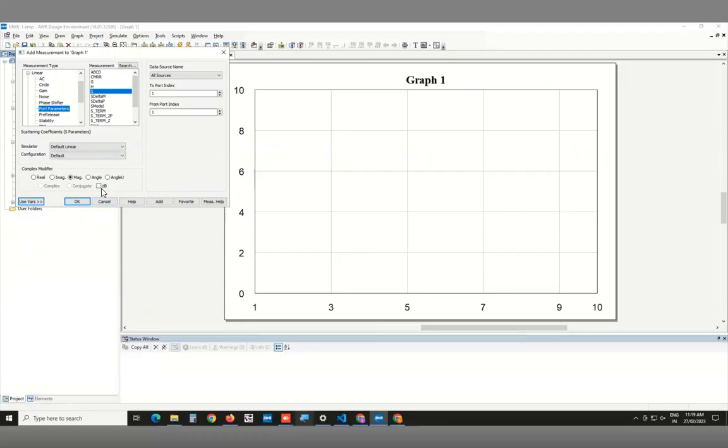So I'm not sure what happened in many of the cases. The default measurement it opens up is also the scattering measurement, which is S11. Since in this case there is only one port, S11 is the only thing you can measure, and that is the same as the reflection coefficient gamma, right? So what gamma are we talking about here?